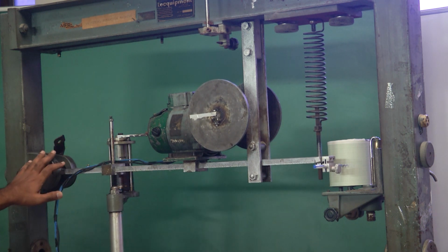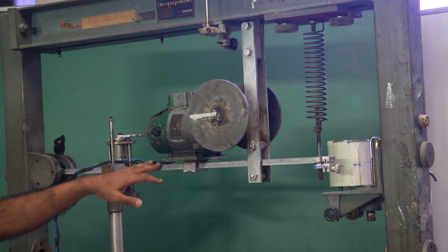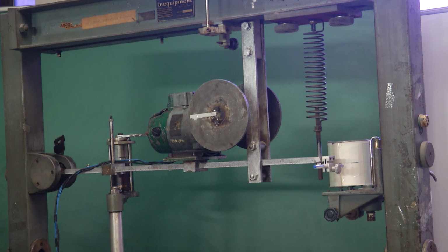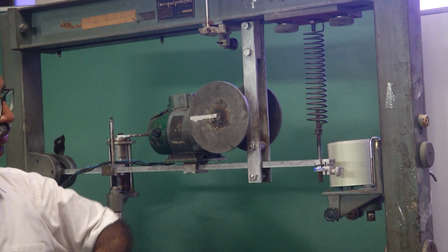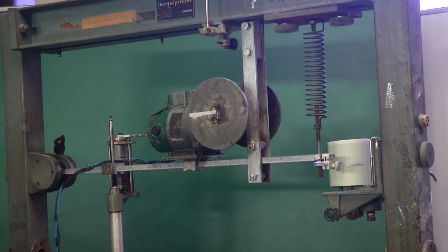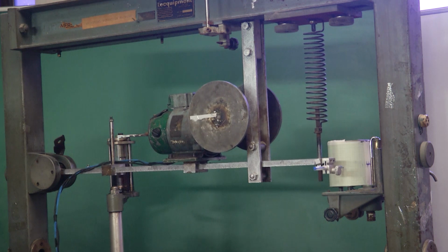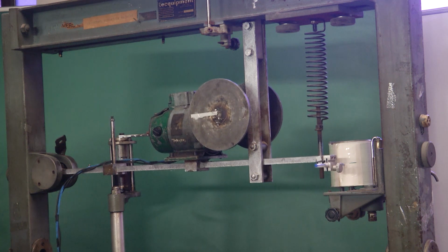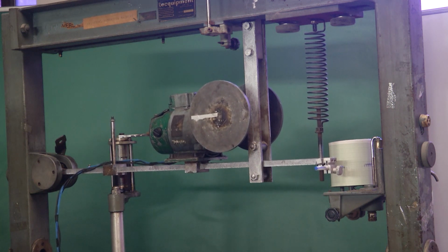In this case, there is almost a remote chance of the beam actually bending and generating strain, but definitely we notice that the spring is getting stretched and compressed, and no matter how small, there would be some hysteretic or structural damping because of the cyclic extension and compression in the material. So, intermolecular friction is going to create dissipation of energy, which gets converted into heat.